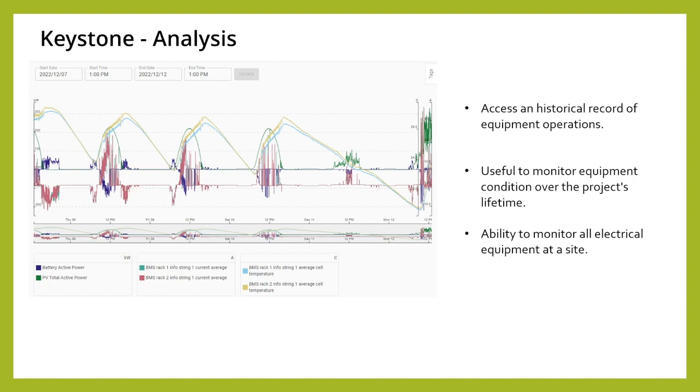So if there is a PV installation on site and panel level information is available, we can capture that. You can trend it over time and you can see, oh, panel 47 is outperforming panel 48 for whatever reason. We can go look at it, right? There's a record kept, a trend of every granular data point that you can get, and this is again really helpful for the operational folks.